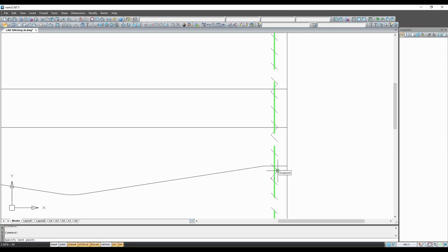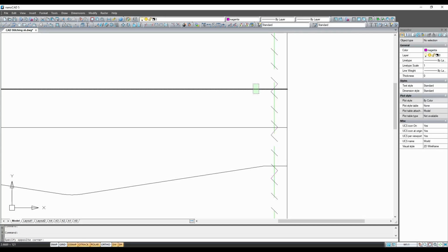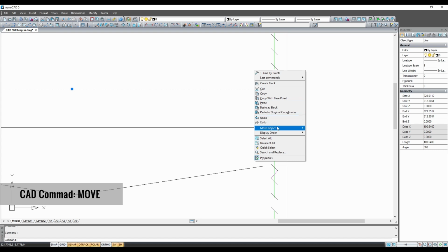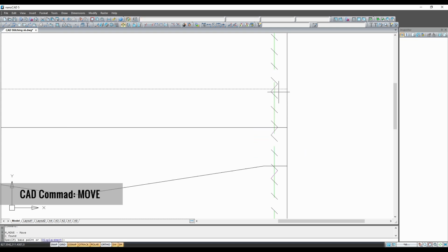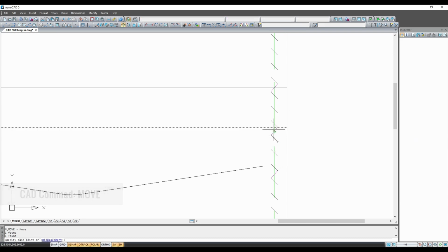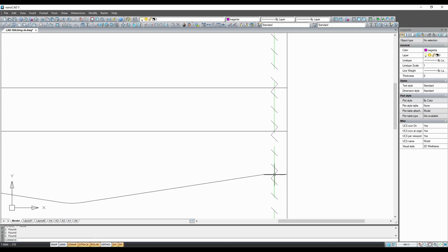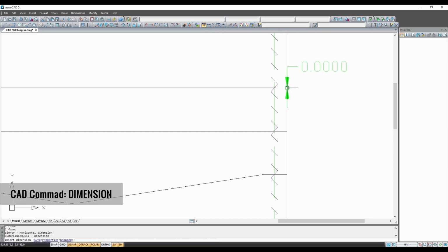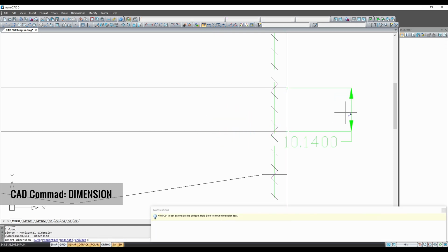In CAD, it is just a matter of moving the tops of your T-pockets so that they are centered between two stitching holes, and then in my case, setting the next T-pocket 3 stitches away. This spacing of 3 stitches makes the T-pocket height equal to 10.14 mm, which will make the prongs of my chisel sit perfectly between the edges.